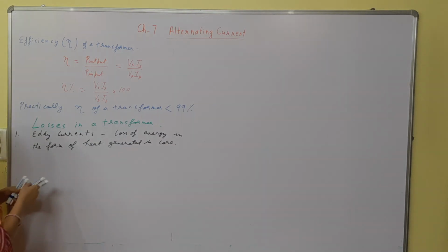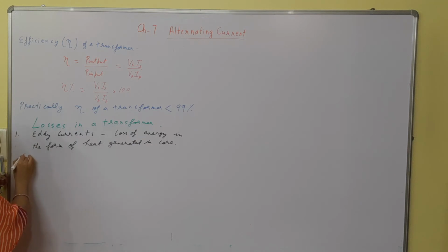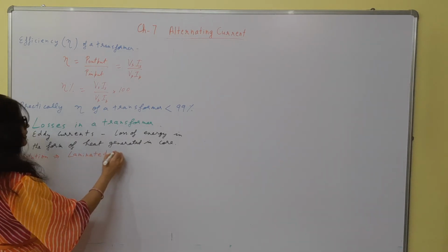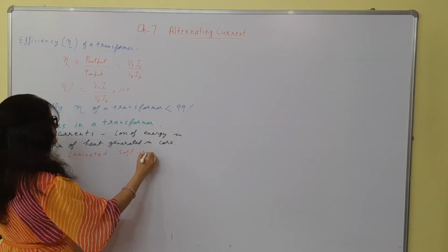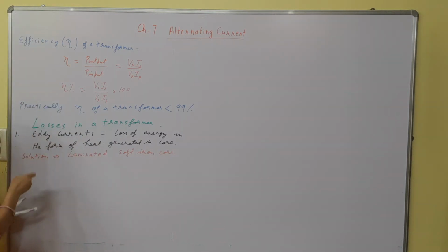So this can be solved by taking laminated core. What is the solution? Laminated soft iron core. Why soft iron? We'll discuss in the second point.